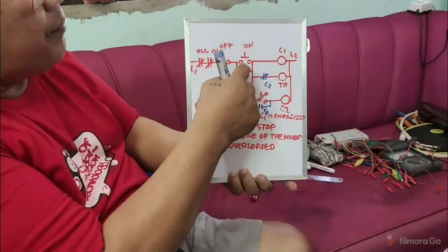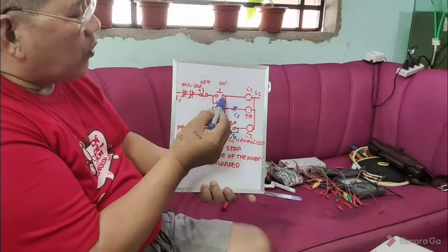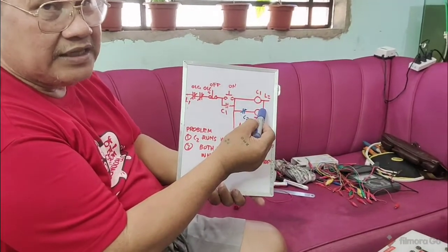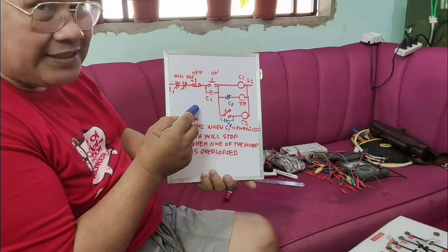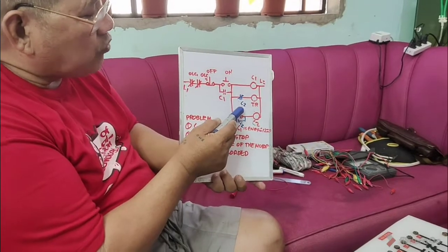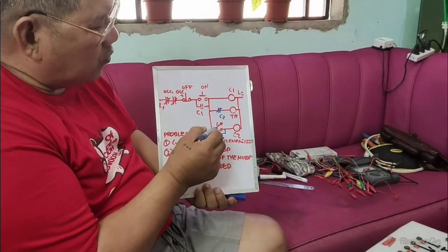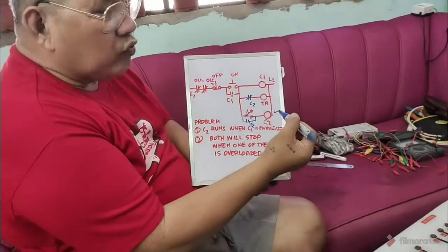So again, I will press the button here. This one is energized. This will close. Okay? And this will also energize the holding coil of the timer. After a few seconds, the timing contact here will turn on, energizing the conveyor 2.